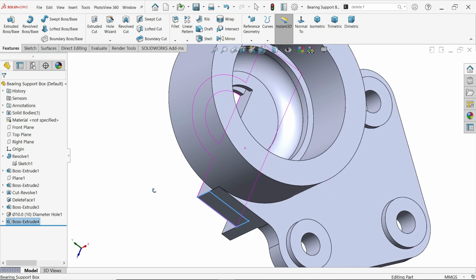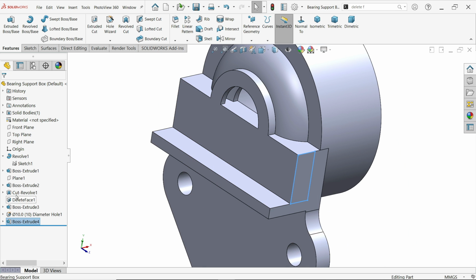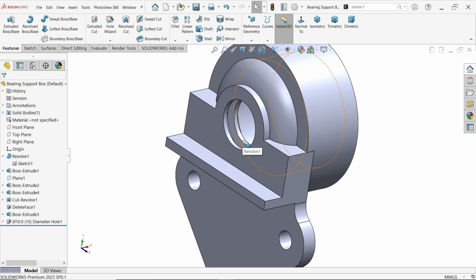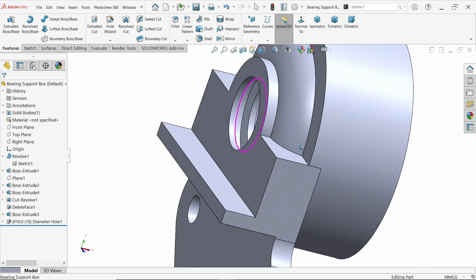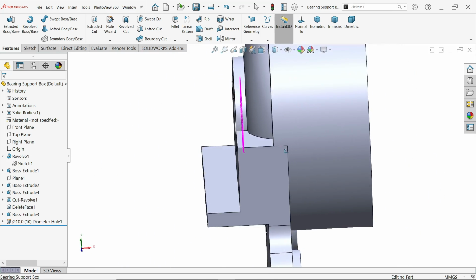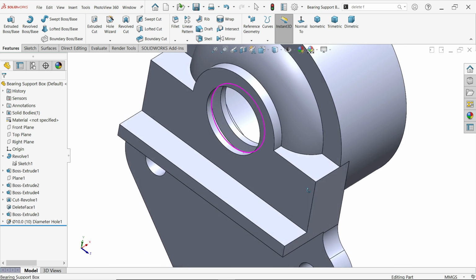But look, again we have to change the position, drag this upside to here. Is still not. Now that's fine. Now this option should be upper than this, extrude cut. Because after the cut we have a clean body inside, and this is our geometry perfectly.